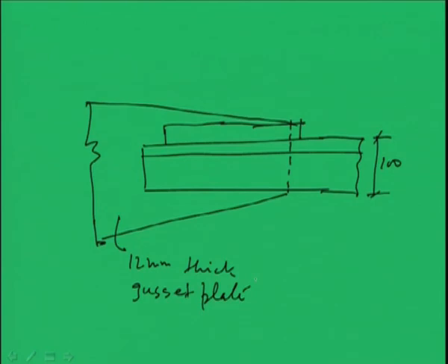this is one. Second thing is this is ISA 100 by 100 by 10, the section of the main angle. Now, the main angle is connected to the gusset plate with a number of 5. So, 1, 2, 3, 4, 5. 5 numbers of rivets are there. Okay. And the lug angle and the gusset plate have also 5 numbers.